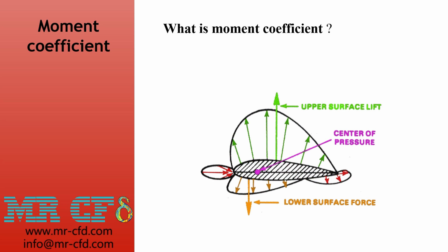The moment of the lift force changes in proportion to the square of the airspeed. If the moment is divided by the dynamic pressure, the area, and the chord of the airfoil, the result is known as the pitching moment coefficient. This coefficient changes only a little over the operating range of angles of attack of the airfoil, but the change in the moment slope against the angle of attack shown in the figures, which are available in aerodynamic books if you search for them, seems very steep.